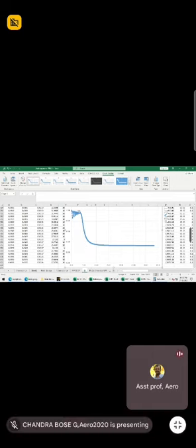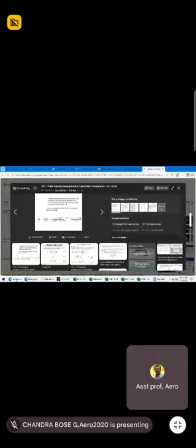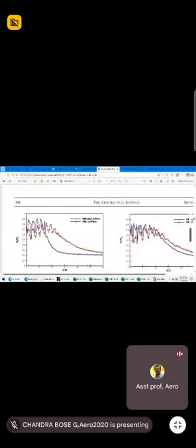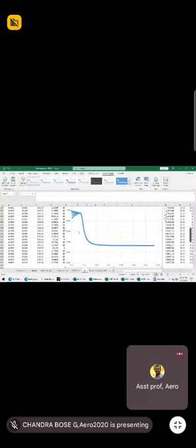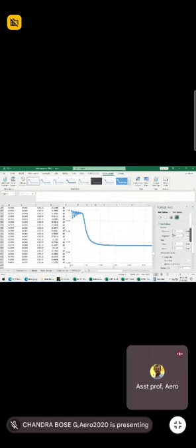So your center line total pressure will look like this. You can enhance this diagram. You can see the nozzle looks like this. So this is our nozzle's center line total pressure. You can change the axis orientations and all. You can keep the maximum 30. It will look better.